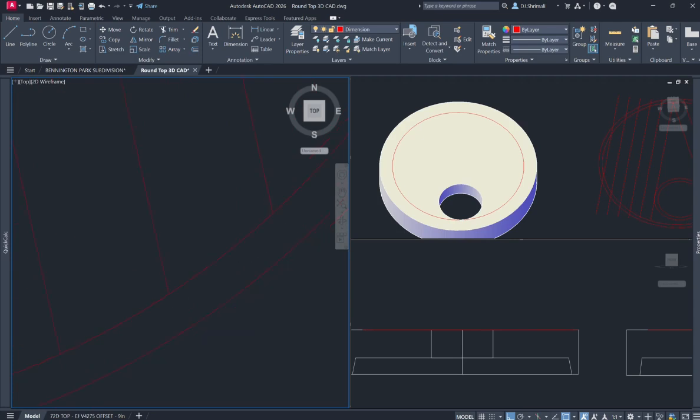So as you can see, I created the rebars for that, number 5 and 6, and I'm using the trim command to trim all the rebars. You can also use the mirror command, just create the rebar on one side and then just mirror it on the other side. That will be faster.